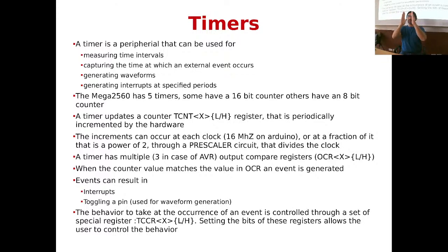And by altering the duty cycle of this square wave, which is, you consider a period of the square wave, and normally you have a period which is 50% of the time high and 50% of the time low. This is how we all imagine the square wave. But if we had a square wave that has the up part for, I don't know, 75% of the time, and the low part for 25% of the time, then that would still be a square wave. Now, this square wave can take only two values, either 0 or 5 volts, or 0 and VCC.